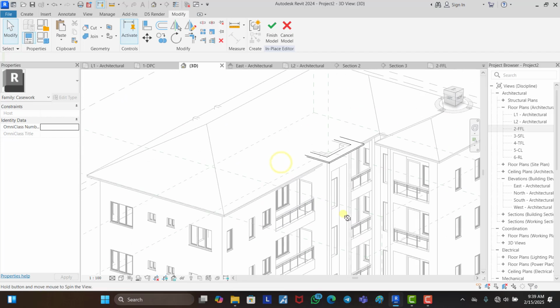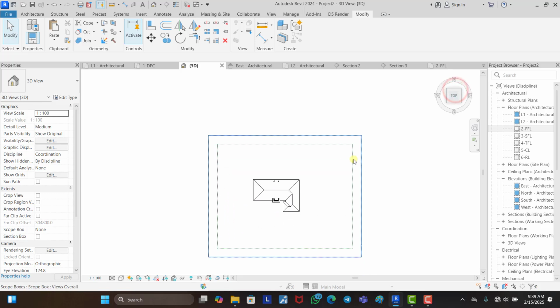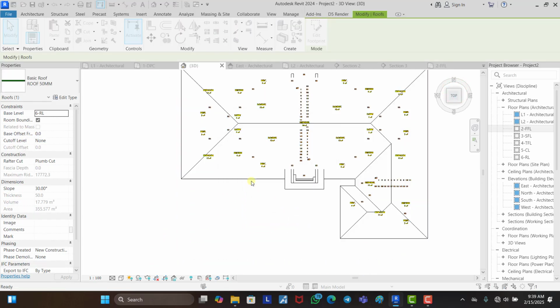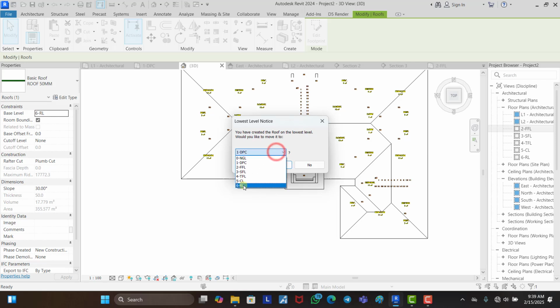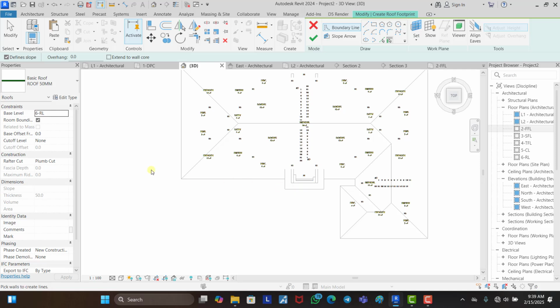You can see how it looks. So we click on finish, and this is it. Then we come to the top view. You click on the roof, CS to create similar, select yes, roof level, yes. But since this one came up 600 base offset from the roof, we're going to come up 600 as well, base offset. Then we can draw our roof now.